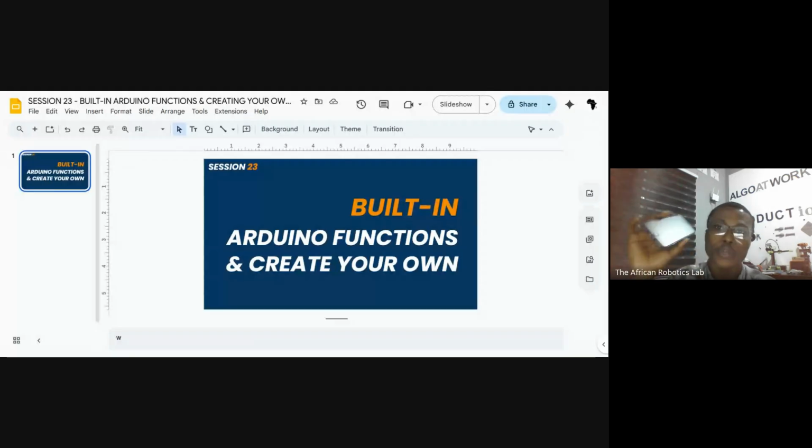So if you are building a battery-powered system, then you can go for an integrated circuit that will be responsible for charging the battery. It will take 5 volts from your charger, and then little by little charge a battery that has been connected to that integrated circuit. But if you are building a system that is going to be connected straight to the socket, then there is no need to go for an integrated circuit that will be used for charging a battery, right?